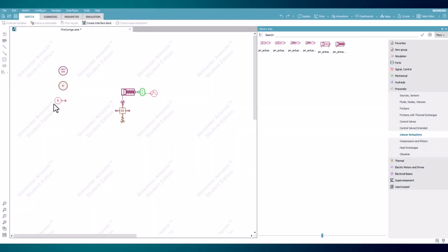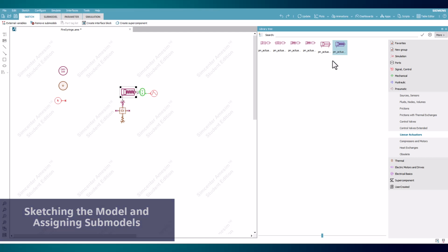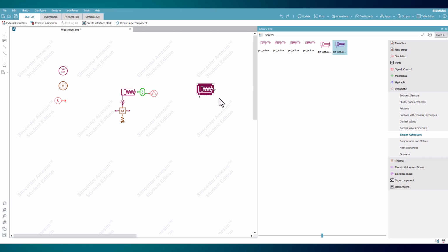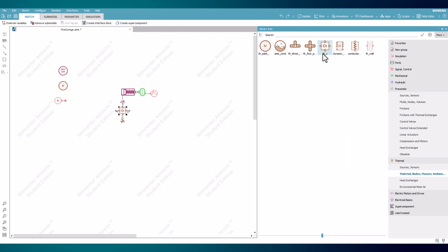In AimSim, the model used begins with a single pneumatic chamber, single rod jack with spring assistance component from the pneumatic library. This component will reflect the syringe with the chamber and air within corresponding to port 1. From here, a convection exchange component from the same library is attached that will reflect the heat exchanged between the chamber air and the cylinder wall. The cylinder wall is characterized by the thermal mass component that is attached to another convection exchange component to reflect the heat transfer between it and the external air. The remaining thermal mass ports can be plugged.